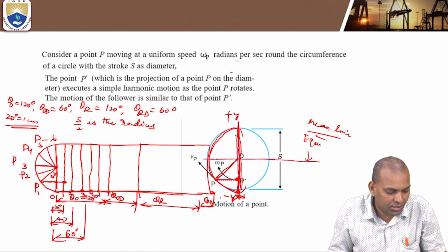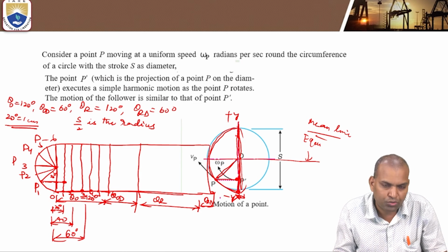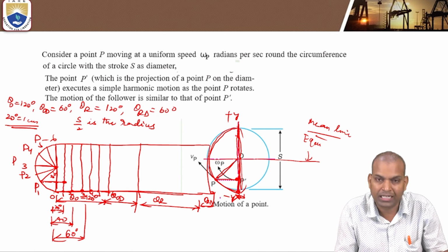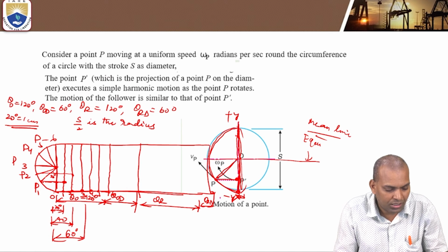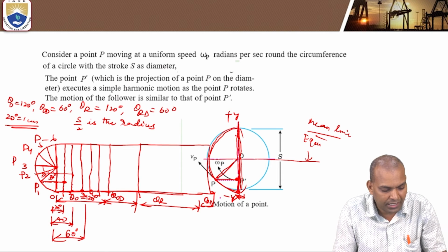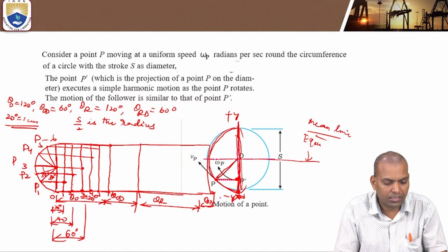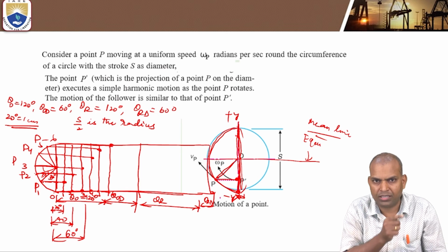Next, P2 is 40 degrees. At that time, where should it fall? That projection of the point P2 on the 40 degrees of cam rotation, what is it? That is the second vertical line. Now, the third vertical line is 60. Each is 30 degrees, divided into parts. Now, that is 90 degrees. So each motion completes how much? 120 degrees of cam rotation.